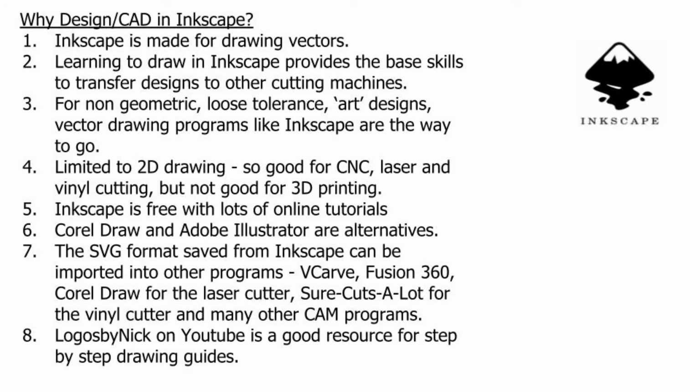So when would you use Inkscape for your CAD or your design work? Well, first of all, Inkscape is made for drawing vectors, so it's good from the beginning. Learning to draw in Inkscape can also help you with projects on the laser cutter and the vinyl cutter as well. It's really good for non-geometric, loose-tolerant art designs, and I'll talk about what that means in difference when we talk about Fusion 360. It is really limited to 2D drawing, so it's good for the CNC laser and vinyl cutting, but not necessarily as good for 3D printing.